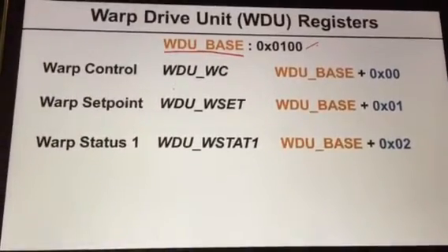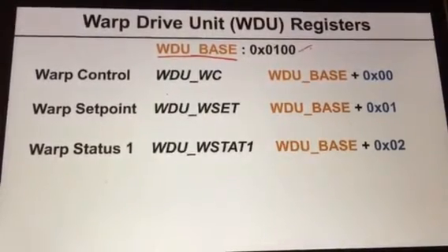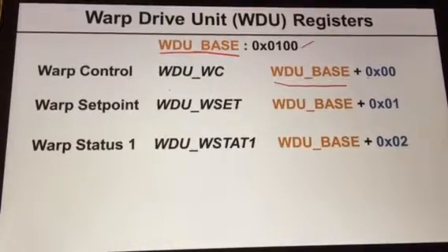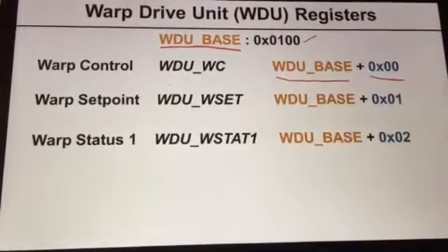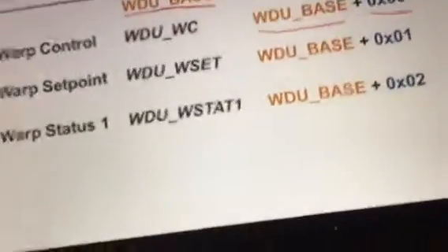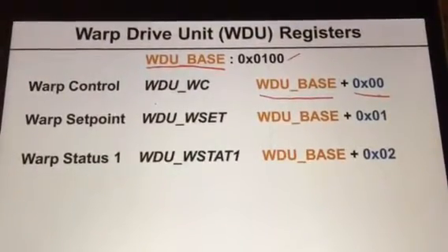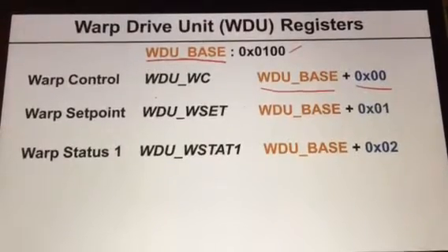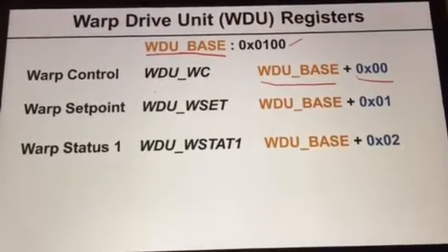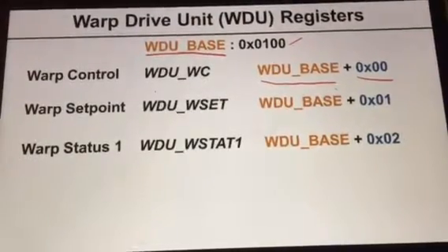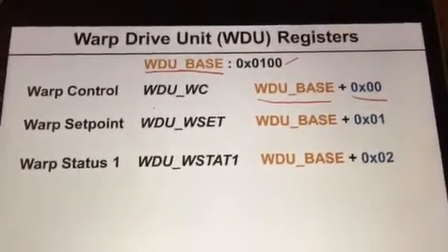And this is very common where we don't necessarily specify the address of each register. We're going to specify them as a base address plus an offset. The reason we do this is that in some cases, some peripherals, there may be more than one. So we just document the offsets, and then the system engineers who made the chip might put more than one copy of the same logic. So this is very common to see this base and then offset notation. And in a future video, when we talk about C data structures, it actually makes perfect sense why they do this, because there are some really cool ways you can use to program it.